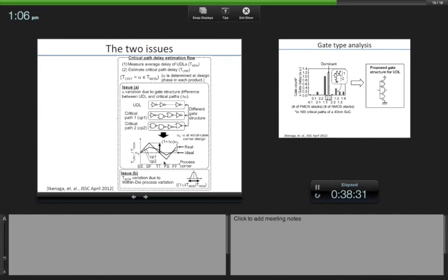But what you find is that there is no single alpha which will give you the exact ratio. It depends on the process conditions, right? Depending on the process condition, this ratio can change, and that is what they mean when they say that there is an alpha, and then there is a small factor delta alpha I need to put in. 1 plus delta alpha times alpha is the actual factor, because then that will ensure that if I put in that number, it will cover the topmost portion, right? The topmost portion. So that delta alpha I have to extract by comparing the delay of whatever delay monitor I use with all the critical paths. Then you choose the worst one and say that is the factor delta alpha I need to put in, right?